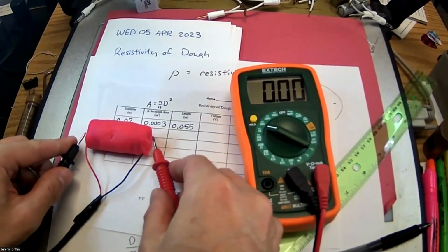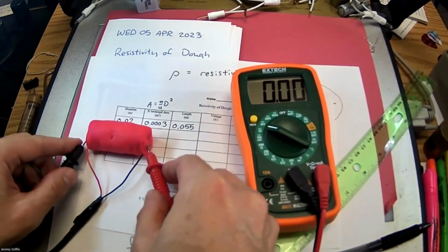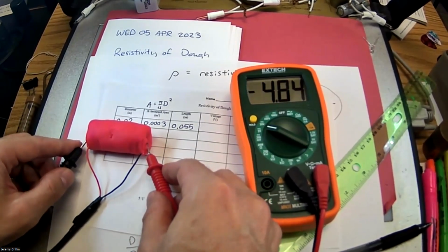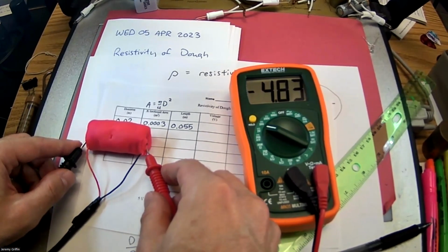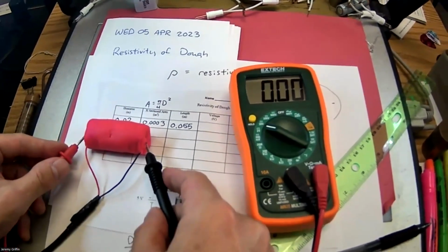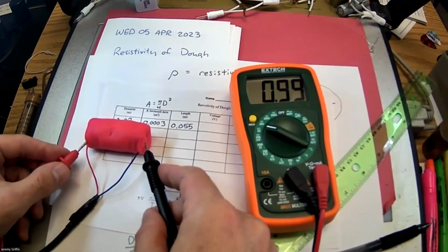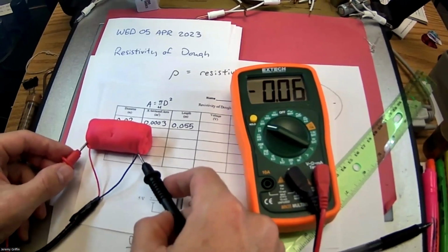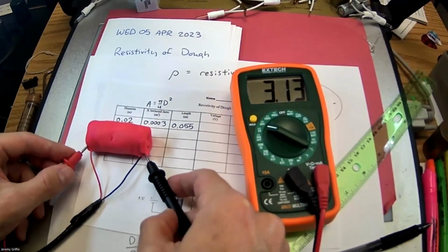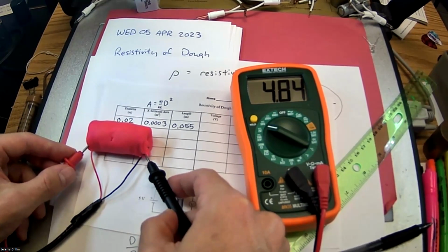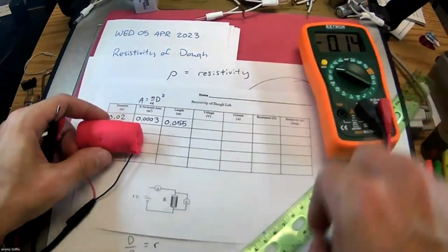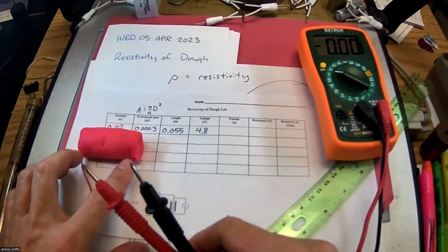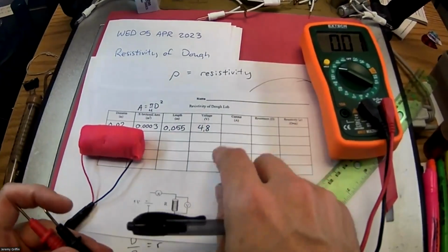Let's see. What's the voltage from here to here? Well, I'd like to connect it directly to my leads. There we go. Oops, I got negative because I got my leads backwards, but it said negative 4.8. Let's see if I get a positive 4.8. Positive 4.8. You guys see that? 4.8? Right. So let's go to voltage. I'm going to do 4.8 volts. And this is a cell phone charger that's about 5 volts. That looks right, plus or minus a little bit.